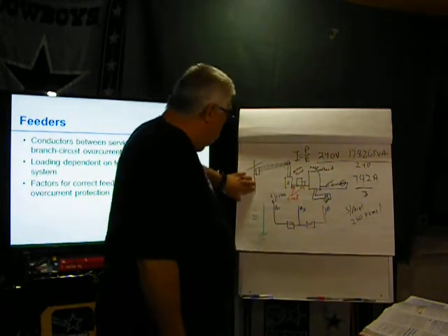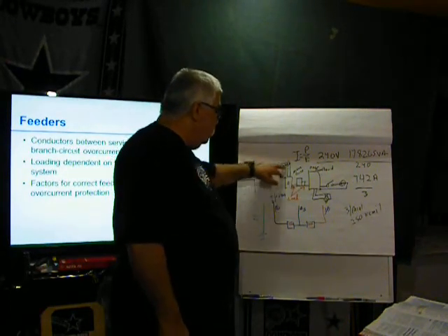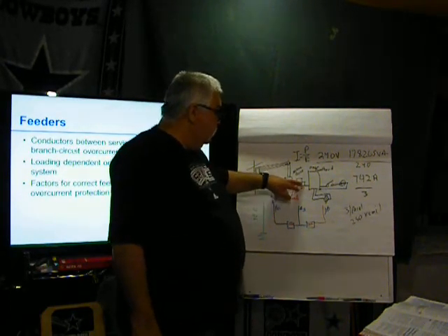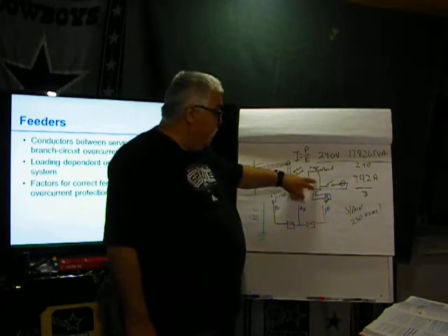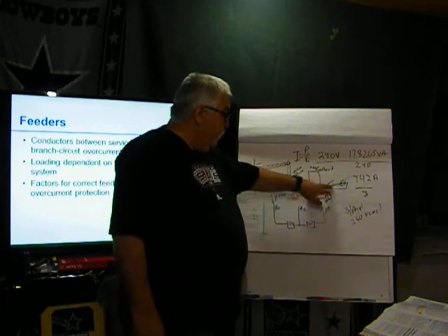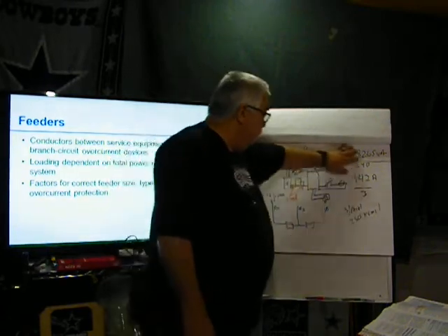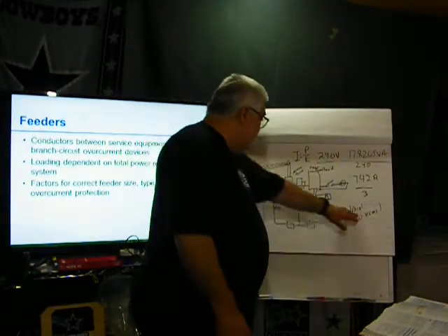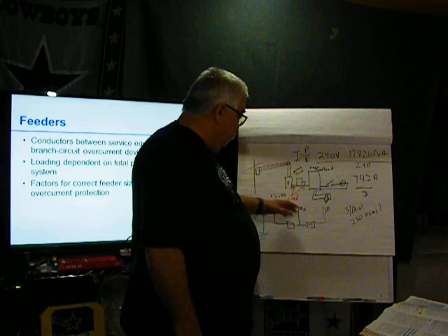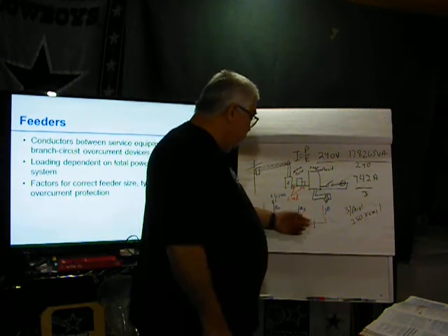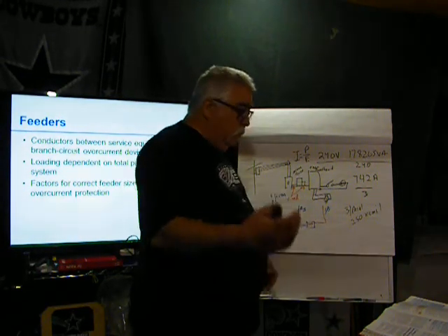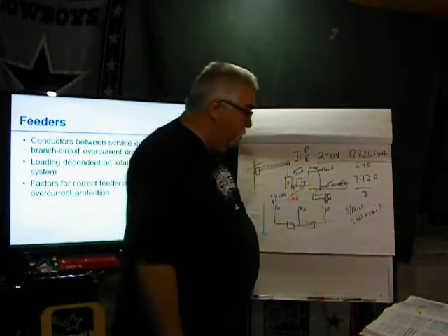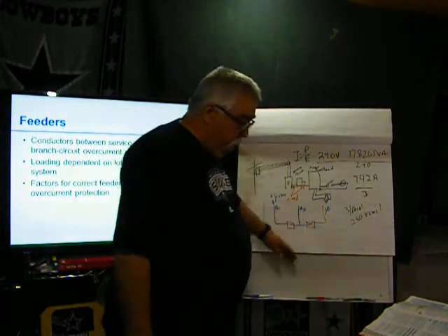So here's our telephone pole, here's the transformer, goes down to the meter, goes to the service disconnect, then it goes to the main panel. Off these main panels, it would go to our branch circuit. Never mind this, I'll get to that in a bit. Okay, this over here, the other sizing of neutral. Neutral only has to carry what the load says, or if it's over 200 amps, you rate it 70%. Okay, so that's that.